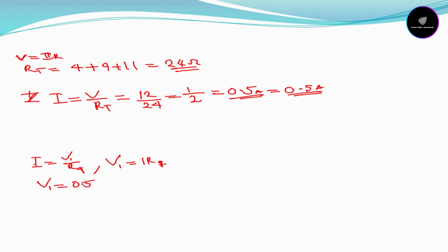Now, the 9 ohms resistor, which is the second resistor, has 9 ohms. So it's going to be multiplied by 9. It's the same thing as resistor 2, the second resistor. From the question, the 9 ohms resistor is also the second resistor. When you multiply 9 by 0.5, this will give us 4.5. That's half of 9. We get 4.5 volts.